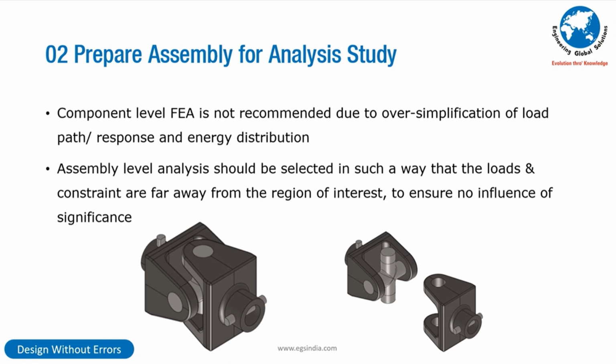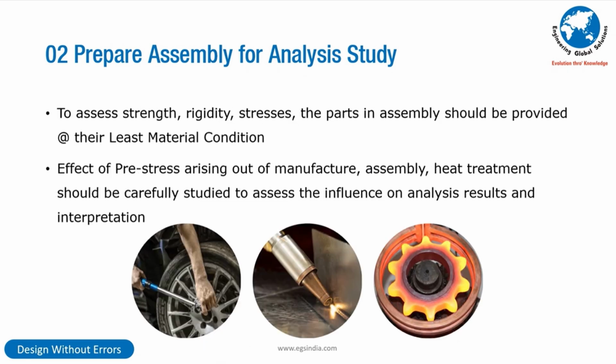So if you are looking at the yoke and the trunnion, then you have to model the next upstream component along with its pin, as shown over here, so that the load path is established firmly through the assembly components. I hope I am clear.